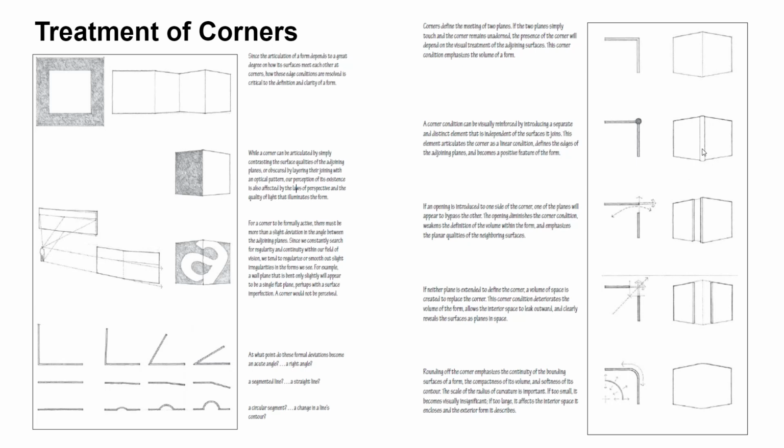So sometimes, in construction or in design, we use the treatment of corners to accentuate the design. This is a treatment which avoids the corner termination and rounds it up to prevent, let's say, chipping or people being bumped by this sharp edge.